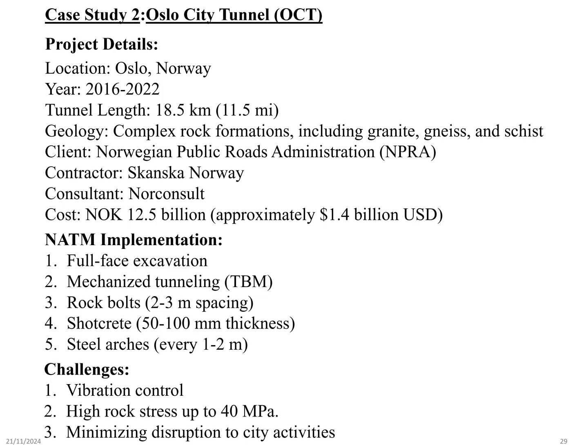NATM implementation: full face excavation employed for efficient tunneling. Mechanized tunneling using advanced tunnel boring machines. Rock bolts installed at 2 to 3 meter spacing. Shotcrete applied in layers of 50 to 100 mm. Steel arches installed every 1 to 2 meters for additional support.